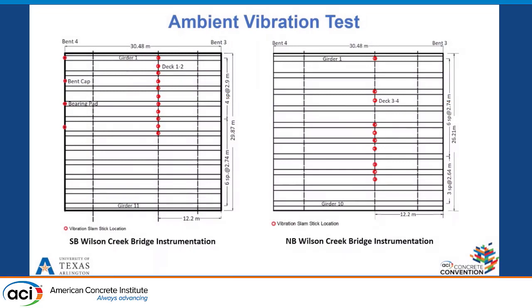Vibration data were collected from the bottom of the girders and some portion of the deck for all of the test bridges. Additionally, some bent caps and bearing pads were also instrumented. The ambient vibration testing plans for the 3 bridges are shown in the figure.